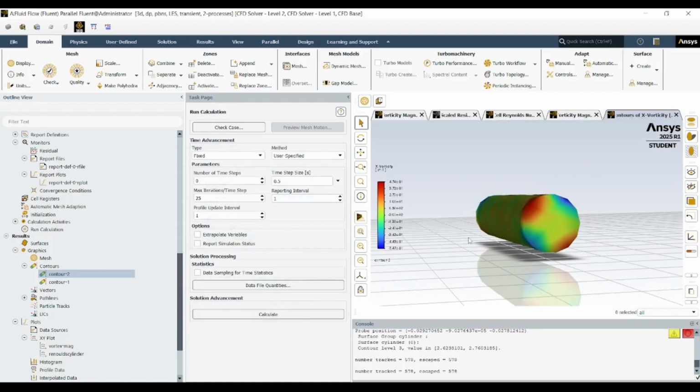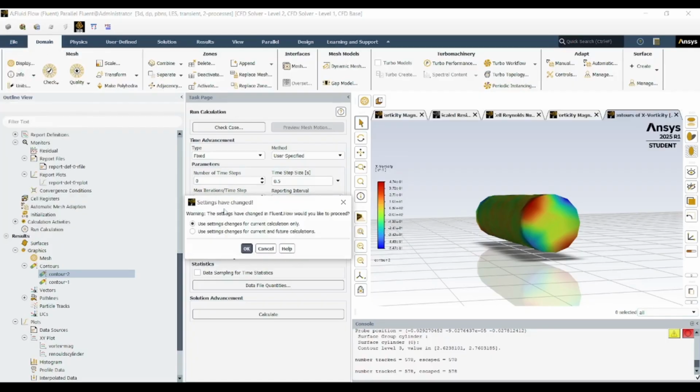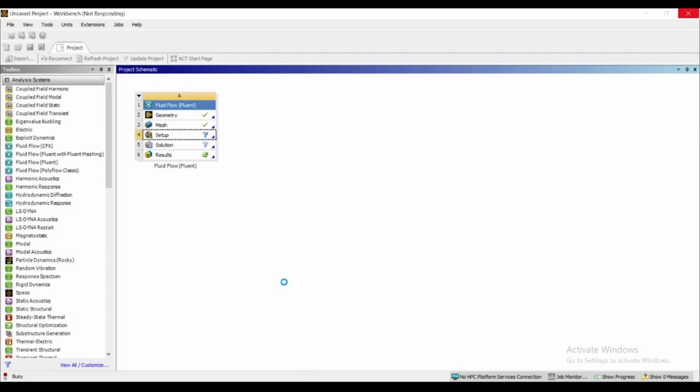Eventually, the energy within this layer becomes insufficient to overcome the adverse pressure gradient, causing the flow to separate from the surface. This separation creates a wake, a low-pressure turbulent zone behind the cylinder, which is primarily responsible for the drag force acting on it. The larger and more unstable this wake, the greater the drag.